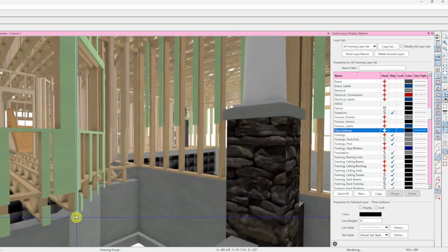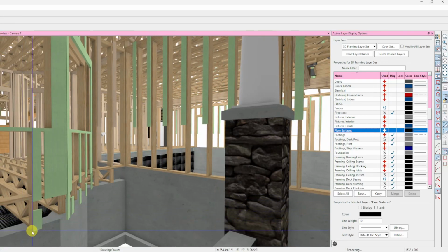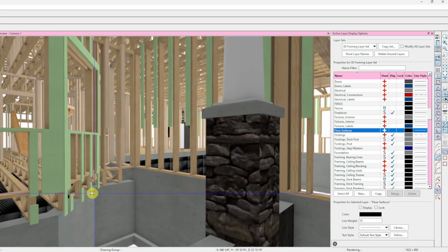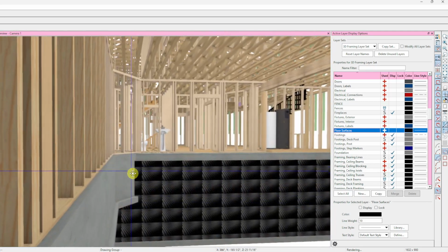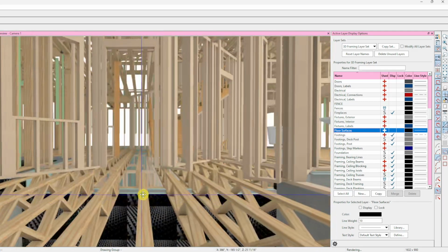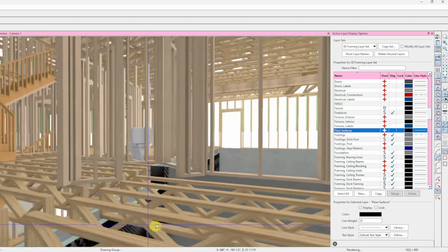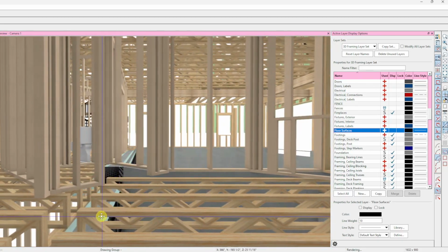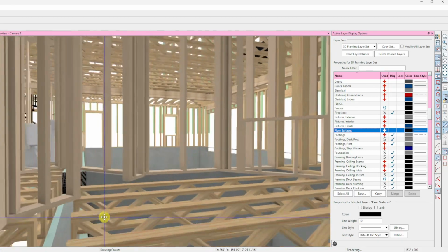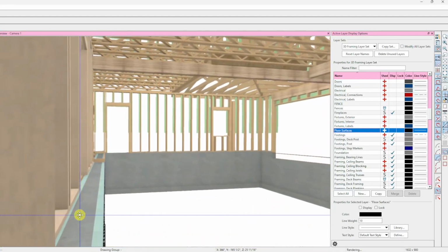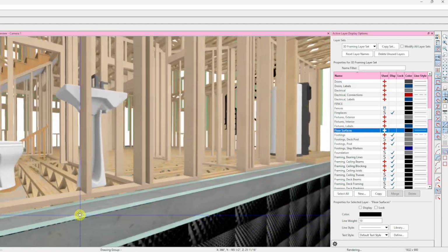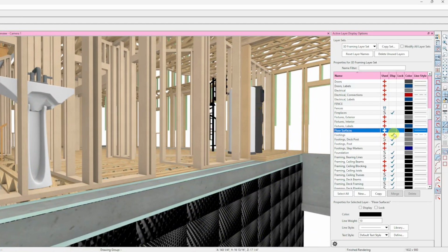So I'm actually going to pull all these back. I'm going to bring the wall up to the bottom of the sill and pull all those back, put a ledger inside. So there's a transition right here because the floor trusses go over the wall and sit on it. And then when I get to here, I need the wall to come up for it to be a slab. But when I turn the surfaces back on,